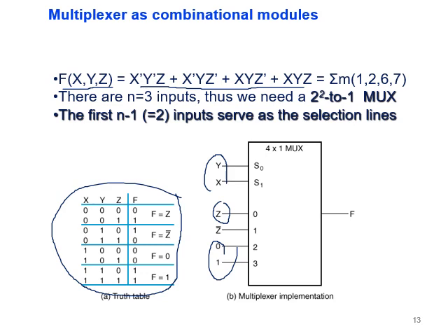If we look at this truth table, and I advise you to follow the situation in this truth table, we will find that the output, which is 1, has 4 min-term expressions. This one says x dash, y dash, z, as you can see here, and the other one x dash, y, z dash, and so on.